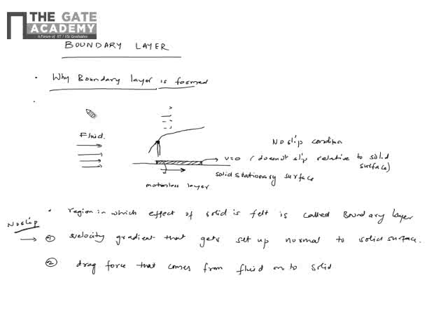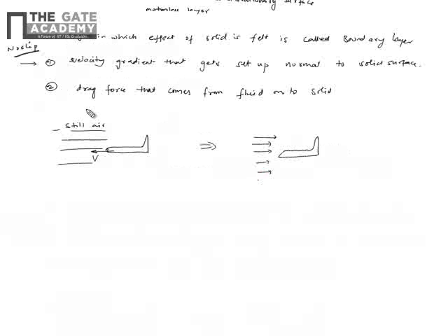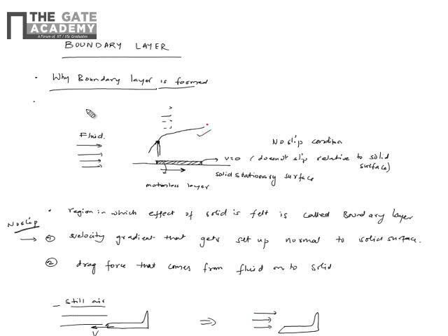This is important because, let's consider an aeroplane which is moving in still air. Now this problem you can visualize as a stationary aeroplane and the fluid moving with the same velocity as that of the aeroplane. Then you can analyze it the way we have started the problem. So you have a stationary aeroplane surface and the fluid moving with velocity v. That's what happens in a wind tunnel.